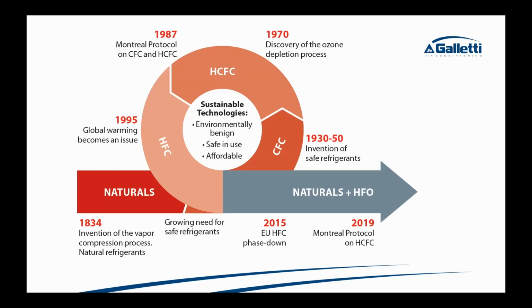the conversation is on PFAS. I'm sure it's been a hot topic with drinking water and the forever chemicals, but PFAS is, I believe, like 2,000 different chemicals identified as PFAS. And some of those identified as PFAS are actually the refrigerants that are blends. So a lot of HFOs, pretty much all of them, are blends. And there are 2 of them that make up just about all of the different blends, like 1234yf, and I'm sure somebody could comment on it. But either way, there are some countries in Europe that are now already banning the HFOs that we shifted to, even 454B, because of the PFAS. So that kind of brings us full circle, like we were saying before, but now with refrigerants.